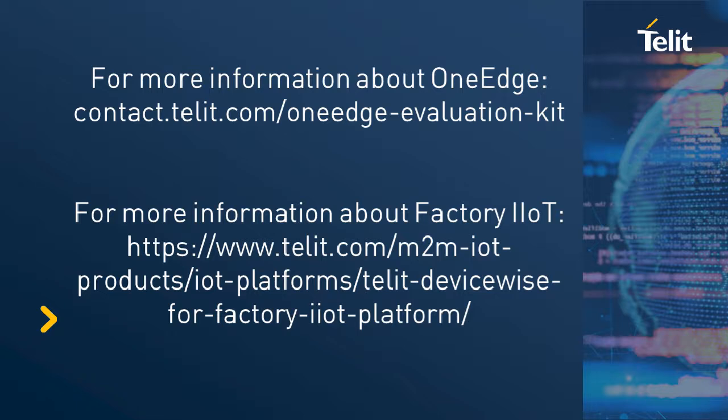You could say it's somewhat similar to MQTT-SN, but even MQTT-SN suffers from the same TCP overheads and the expectations of connectivity, where the lightweight M2M connections are able to survive very long dormant periods with a very efficient session resumption. I apologize if I got a little overly technical in that response, but it's been a deep study of mine how efficient it can be.